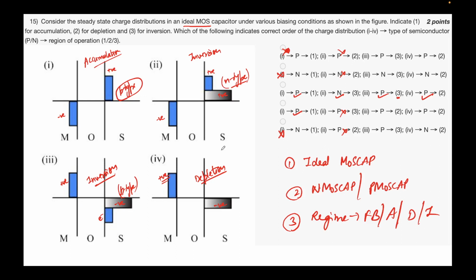Okay, I'll assume that why I keep repeating this problem again and again is because this is actually the very fundamental of what we'll see in the next device, hopefully MOSFET. Unless you have MOSCAP at your fingertips, right now we are applying potential only to one terminal, the metal terminal here. In MOSFET, you'll have 3 terminals at the very least, 4 in some problems. Actually, there are always 4, but we reduce it to a 3 terminal problem.